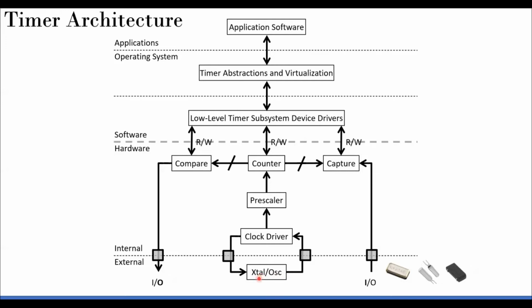That is important because that is a... or you can select the internal clock also, which is predefined, and you don't have any variation from there. Of course, you can pre-scale it. Moment you have a certain clock frequency, you can actually scale that clock frequency, typically reduce that clock frequency, and that provision is there. We'll go in detail about that in the subsequent slides.